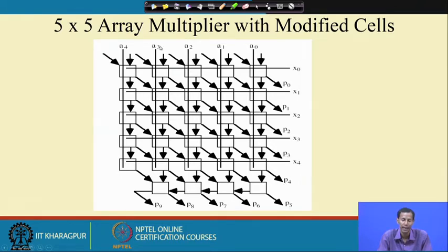That means here I do not have to put this. Initially what we were doing was putting A0 X0, A1 X0, A2 X0, all at these particular terms, but here I do not have to do that. Only one X0 is needed, because the ANDing operation has been done inside these processing element blocks.